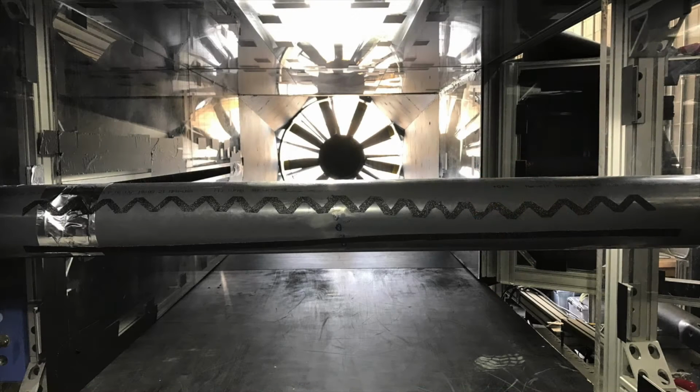According to Slagen, zigzag strips are much more effective in tripping the boundary layer than sandpaper due to the fact that sandpaper requires a thicker strip and tends to create a more randomly turbulent flow. This experiment combined the two methods into one zigzag sandpaper strip in order to more effectively trip the boundary layer. A straight sandpaper strip was used to trip the boundary layer on the lower half of the cylinder to potentially examine the differences in the two tripping methods.